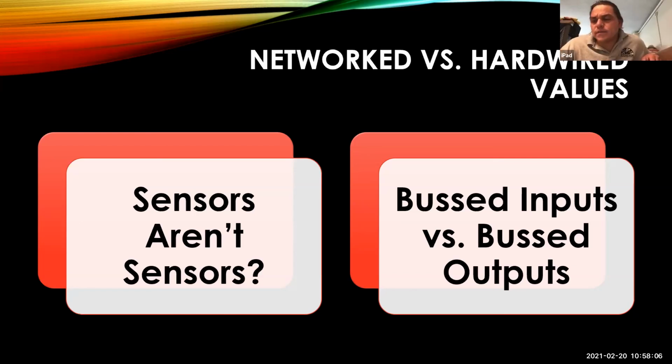Could the computer simulate this value if there was an issue? Could it just substitute a value? Sure, it does that all the time. How do we get 40 degrees below zero out of an IAT? Right. And also, some systems, if the sensor goes bad, give you, based on throttle percentage, the voltage that you should see on your scan tool, not the 0 volts or 5 volts because the sensor's broken. So you see some weird stuff.